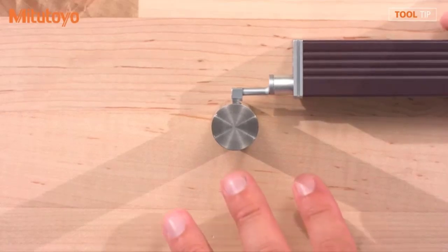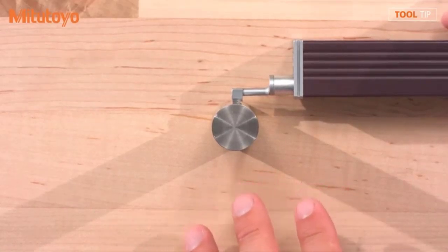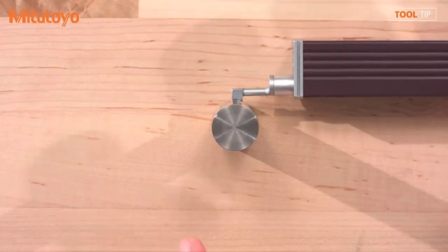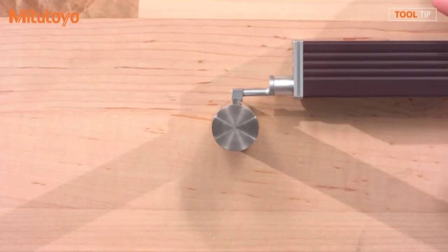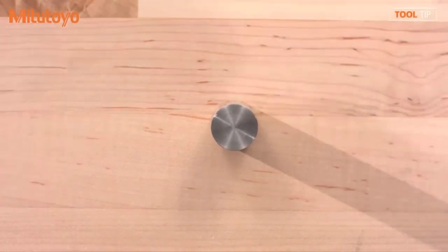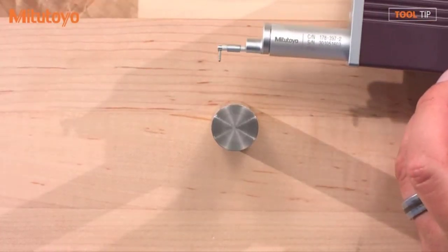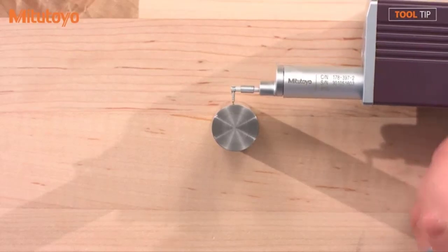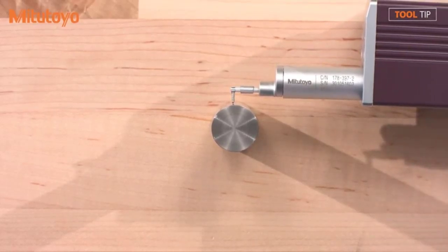That's correct. If I were to take a measurement with this, I could probably spend some time with the setup and get a number that shows up on my amplifier, but that doesn't mean the number is a good measurement that I can trust. So in an application like this, a skidless system would be better? That's correct. You'll notice as I bring a skidless system in for measuring, that by not having a skid, I can bring the stylus in contact with the surface. I'm going to get a very good measurement here. You're going to be able to trust these numbers that you're getting from this unit.